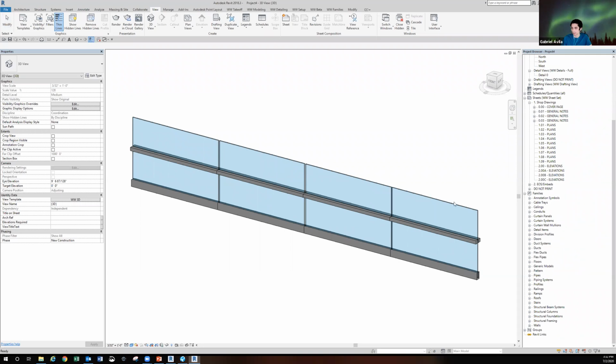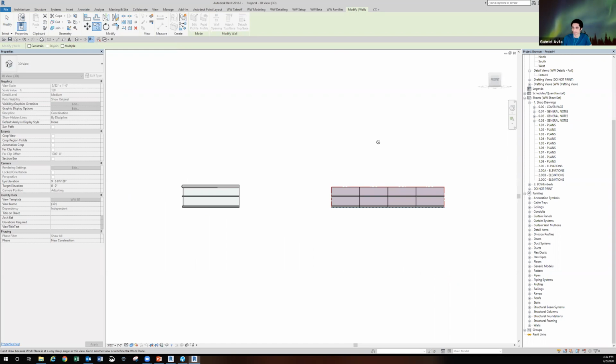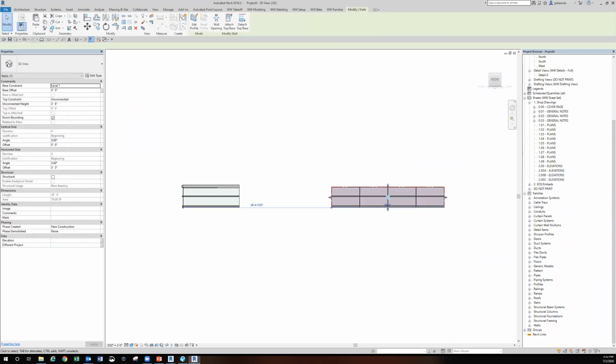Like James mentioned, you could probably use it without the cap in this case, and then make a generic model here that covers the 3 lights. That'd probably be a good way. You could even use a curtain wall on top and just not put grid lines and host just the rail top. It might be easier because you would take the curtain wall you already made, copy and paste it, change everything to be empty, don't have any grid lines, and then host the rail.